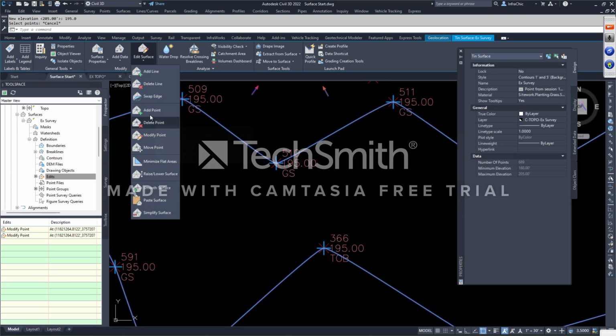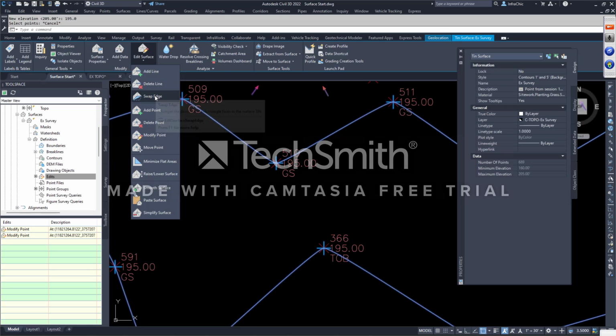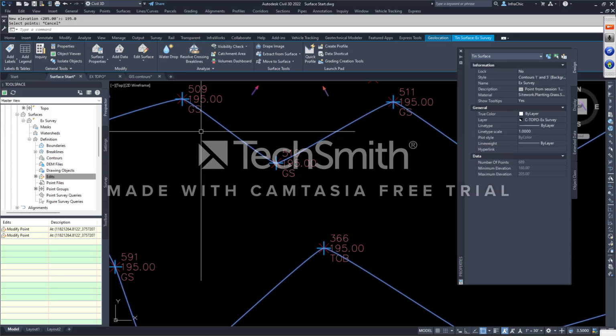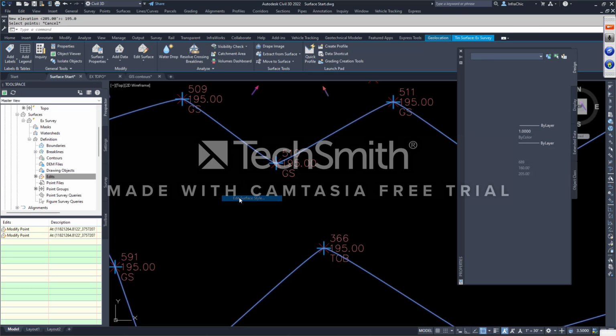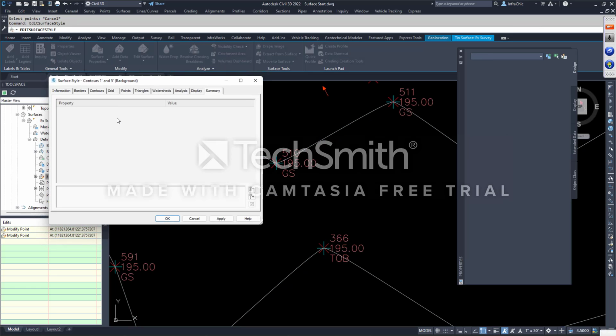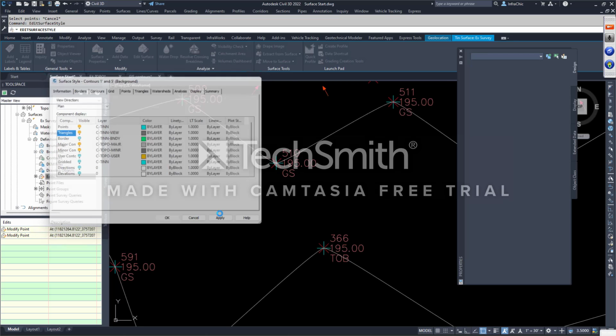There's also the lines. Now the lines, first of all, the style must display the item you're going to modify, whether it's a point or a TIN line. That's what these lines are, TIN lines, okay? Let me turn on the TIN lines real quick. Right click, because it's still selected, edit surface style, and display, and turn on the TINs. To show you how this works, you zoom out.